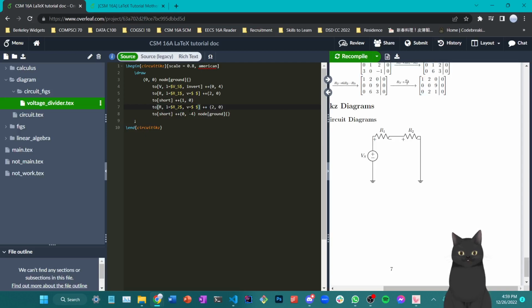You can also see that the space is a bit crowded, so what I like to do is to expand the space from 2 to 3. You see, the good thing about using this relative coordinate instead of absolute coordinate is that you only have to care about the distance between your elements, and you don't have to retune the position of your element every time you change some other difference. So this is actually quite convenient compared to an absolute coordinate system. As you can see, it's rather easy to just adjust the size of a component than have to adjust the distances between their centers. This is a bit inefficient.